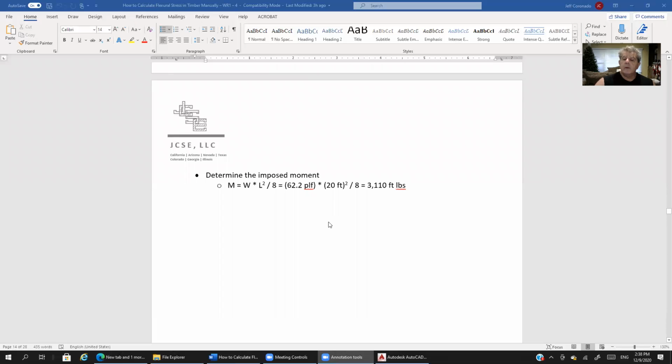Oh, by the way, remember what we talked about, right? Start thinking about these numbers. Start getting a sense for them. So we had a rafter that was about 20 feet long, right? We had a tributary width that was about 2 feet. We had a uniform dead load that was on the order of 11 pounds per square foot and a live load on the order of 20 pounds per square foot. Let's see how these numbers play out, right? We need to get a feel for, at the end of the day, do these numbers check out?